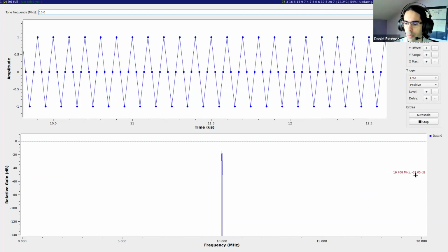And even this is just an example, but the RTL SDR can receive signals up to 1 gigahertz point something. It depends on the exact model you have. So having something which costs only a few dollars, being able to sample at 2 gigahertz, which is what you would need to sample those 1 gigahertz signals, would be impossible. There are analog to digital converters, ADCs, which are capable of sampling at 2 gigahertz and above, but they are somewhat pricey. So how does the RTL SDR operate?